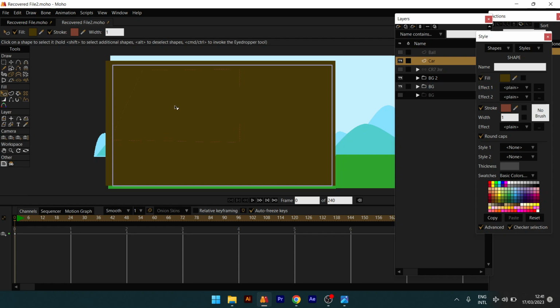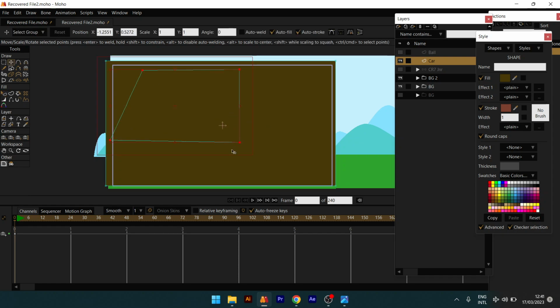All right, so those are two shapes on one layer, shape 1, shape 2. I'm going to hold down my shift key to select the two shapes, so shift, select this, select this. I'm just trying to bore a hole through this shape.